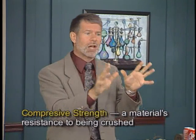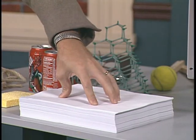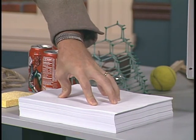So compressive strength, that refers to a material's resistance to being crushed. If you push down on an object, if it crushes or caves in like a pillow, it has low compressive strength. But if it can withstand a very heavy weight without deforming, that's like a brick, it has high compressive strength. Materials with high compressive strength must have rigid frameworks of atoms in at least 2 directions that are perpendicular. I like to illustrate this with an ordinary stack of paper. I mean, a stack of paper is not strongly bonded together, but if you push down on it, it's got strong bonds in 2 directions, and the stack has great compressive strength.